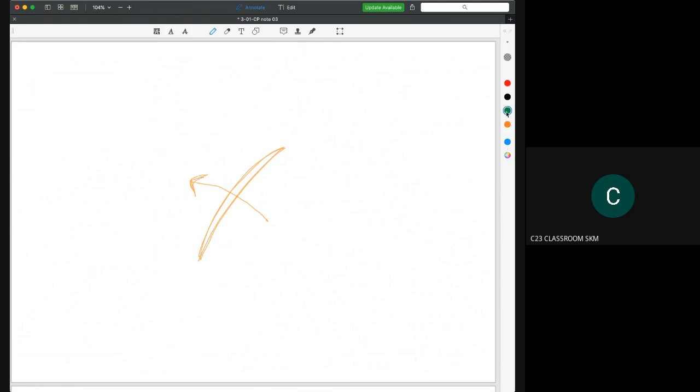So the second step is you need to draw the actual velocity. The idea is simple. If your rotational speed here is from right to the left, so for sure the absolute velocity will become this one, meaning it also moves from right to the left. Okay, so we draw the actual velocity as V1 and V2. Point 1 here is the inlet, and point 2 here is the outlet.